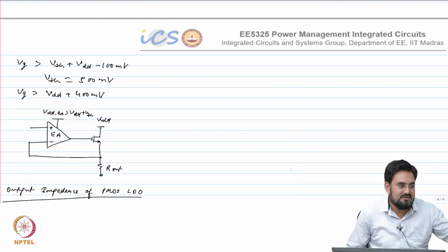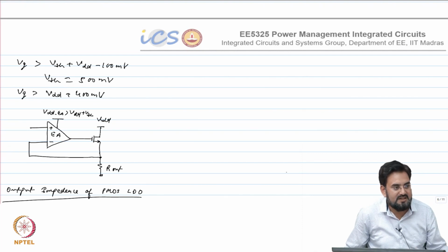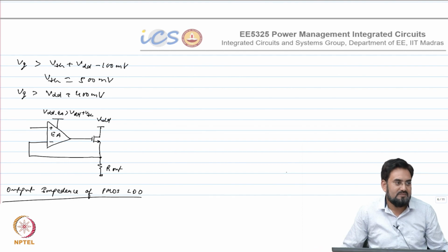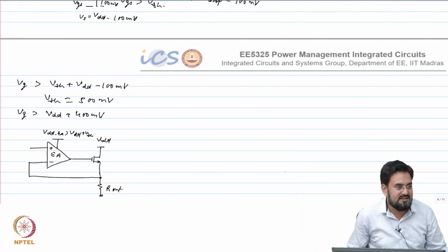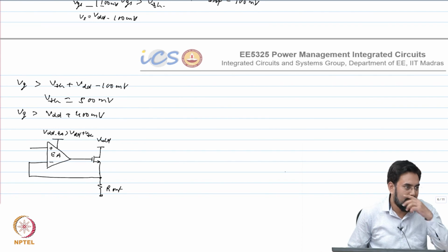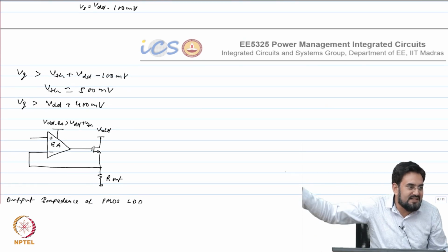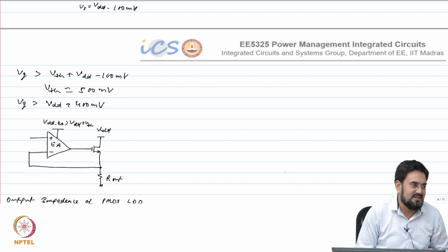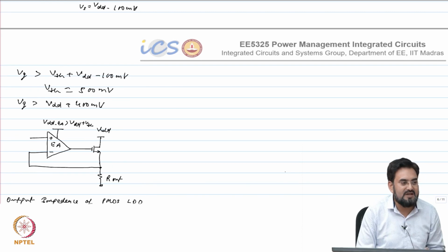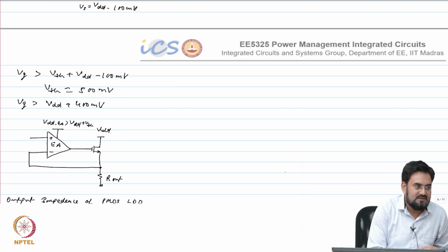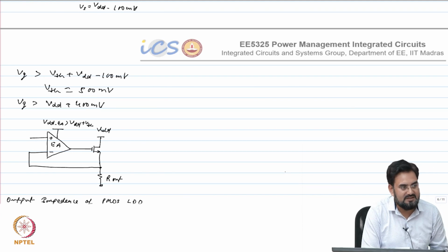You will get a zero if you make the first pole dominant, and if you make the output pole dominant, you won't see that zero. So that is why I said if you make the output pole dominant, it not only helps in improving your transient response, but your PSRR also, because any AC at the output will be absorbed by that capacitor. So increasing that output cap, making it dominant, will help in all the cases.